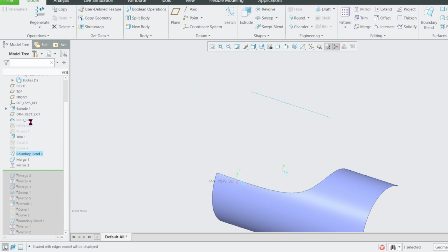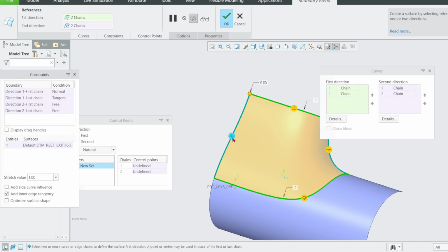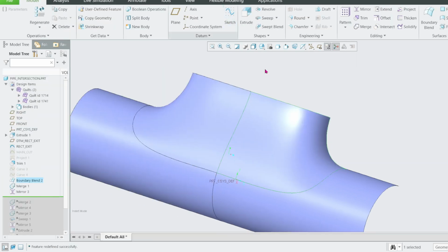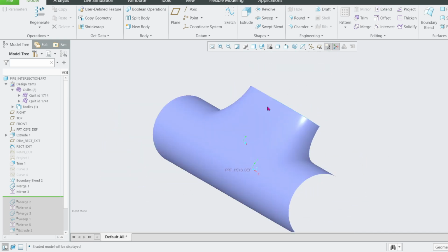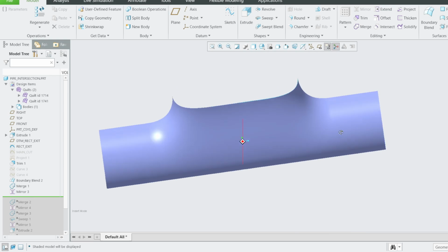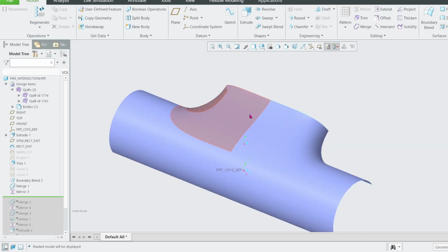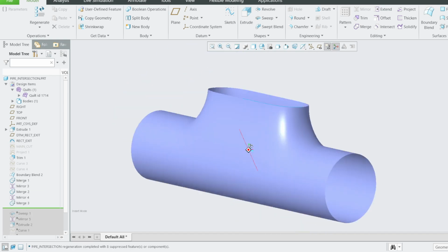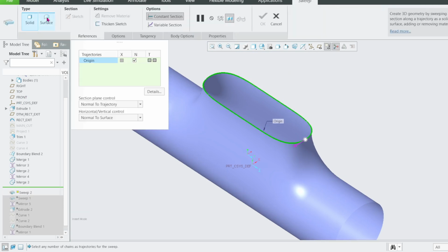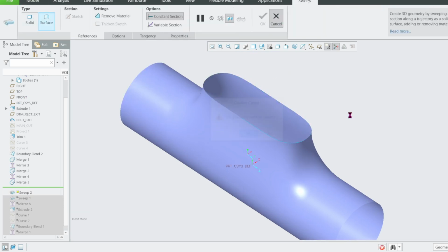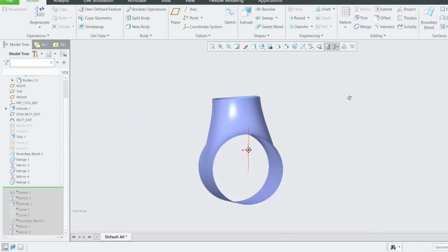The simple fix is to go back now to your curve here. Remember this three. We should have now normal and normal. That solves the problem. You go to shading, the edge disappears. There's no edge. You can see it's now smooth, very smooth. If you now go here, it's very smooth. Still you can't sweep. Okay, you can see how smooth it is.